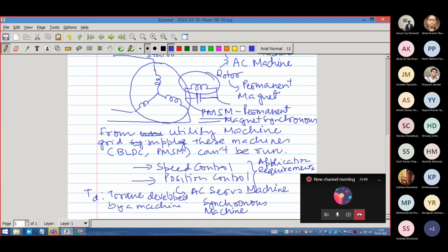And you already know that the torque expression is essentially what? Flux of the machine and current of the machine. I'm not defining it too precisely here, with all sorts of assumptions. This phi is the magnetizing flux, the flux that magnetizes the core, and I is the current in the rotor coil. With this general definition, I can say that any machine is a torque generator, nothing other than a torque generator. The machine doesn't understand what speed it is running. It is dictated by the external world.